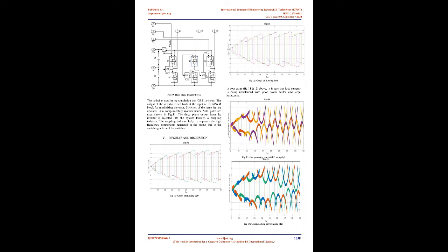In [10], the ANN-based current control of SAPF is presented. The error signal is provided as an ANN input, and the ANN produces an appropriate switching signal for harmonic and reactive power compensation to the SAPF. In this method, a fixed switching frequency operation is achieved.